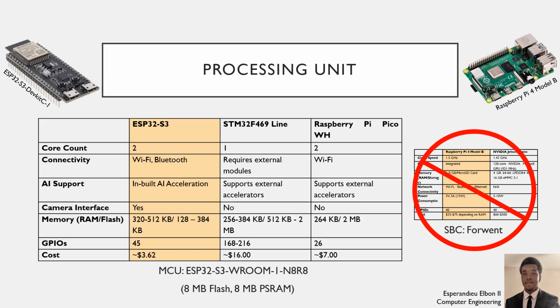system's primary SBC. Before finalizing the decision on processing unit composition, a decision on which movement algorithm to use was made. This will be discussed in further detail later in the presentation, but for right now, it should be known that a simple random walk was chosen. Almost any MCU can manage the overhead of this algorithm, and so the Raspberry Pi 4 was deemed unnecessary.